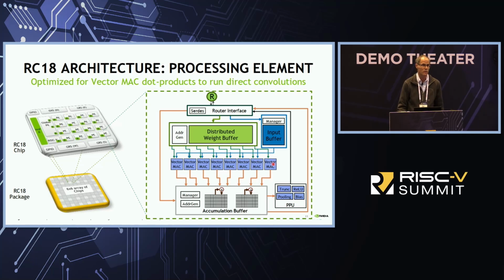It's a pipelined multiply accumulate block that is designed for very high performance, where you basically can take in a new set of samples on every clock edge and do all the multiply accumulates and stream them in and stream them out without any gaps. And basically, this entire processing element is fully designed in C++ and fully implemented by Catapult high-level synthesis in 100% pipeline fashion to achieve optimal utilization in the hardware.